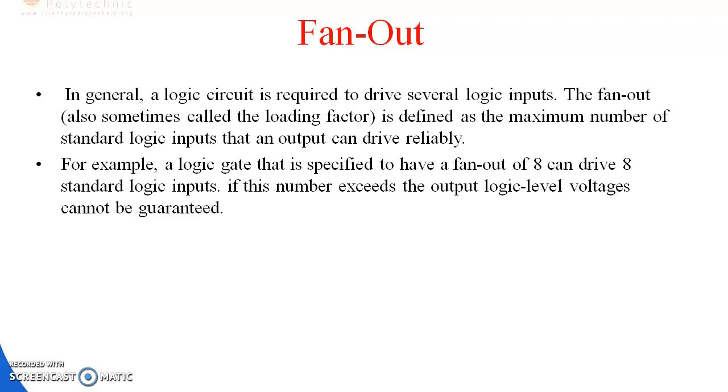So the fan-out of a logic gate is the maximum number of standard loads that the output of the gate can drive without impairing its normal operation. For example, a logic gate that is specified to have a fan-out of 8 can drive 8 standard logic inputs. If this number is exceeded, the output logic level voltages cannot be guaranteed.